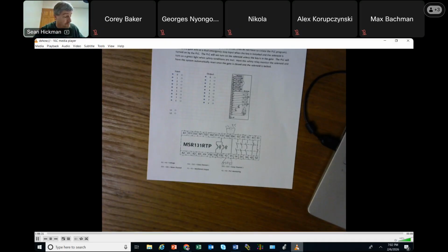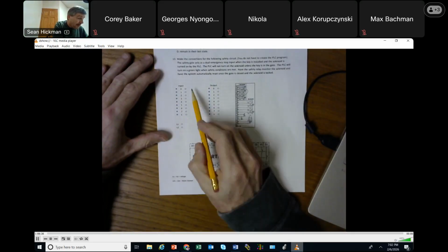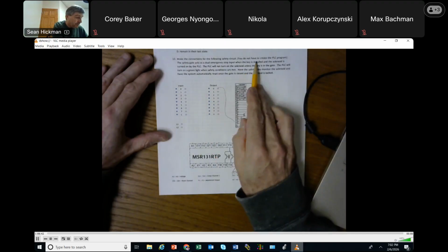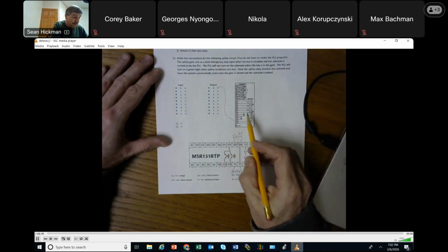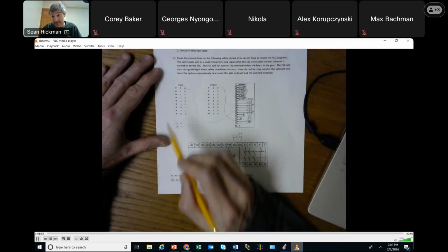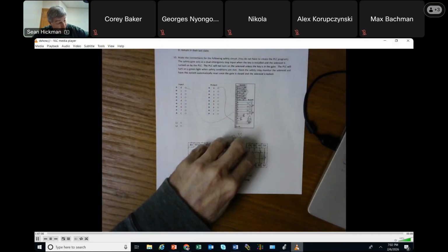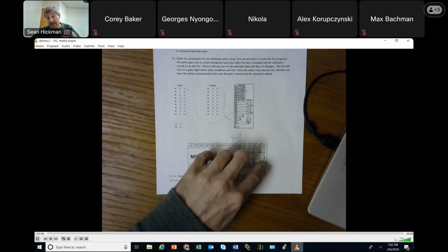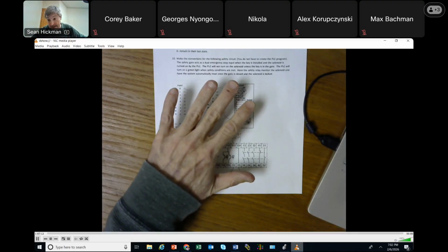Things like that. So a lot of different ways here. It said that you turn it on the solenoid. So this output right here runs that solenoid. The key is install the solenoid. The emergency stop key is install the solenoid. So somehow I needed an input here running to the input there. I mean, there's just a lot of different ways that you could set this up to have the relay monitor this and have the PLC monitoring the safety relay through these contacts, and then finally, I think we got a pretty good idea of the safety contact side of this.